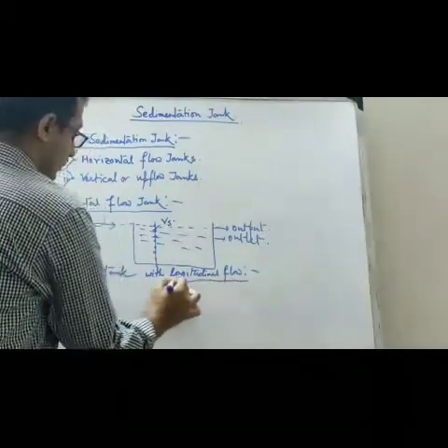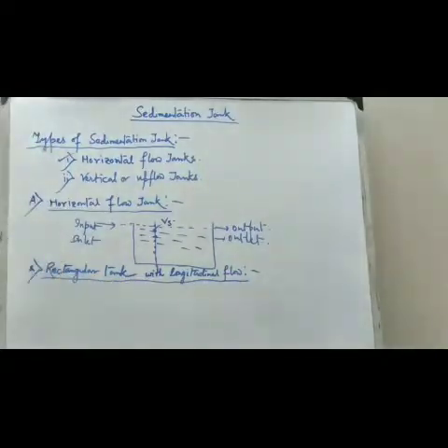This is the first type of horizontal flow tank, and this type of tank may be provided with a mechanical scraping device to scrape the sludge to the sludge pit located usually towards the influent end, and from where it is continuously or periodically removed without stopping the working of the tank.